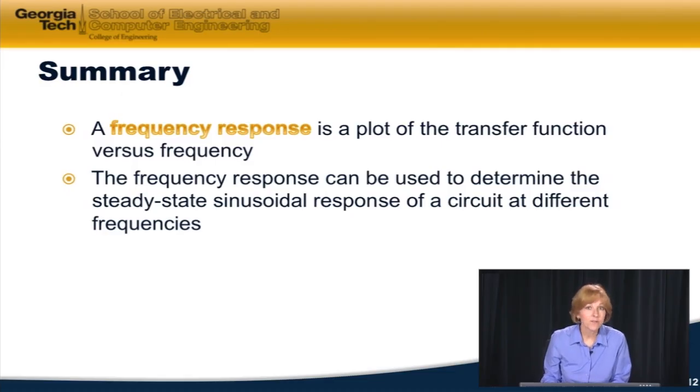Does it attenuate frequencies in certain ranges, or does it amplify signals or make them larger? Like that last case with the resonant peak, we had the output greater than the input. If we take a look at the transfer function and the frequency plots, we can understand what's going on. Is it amplifying or is it attenuating? And if so, in what frequency range?